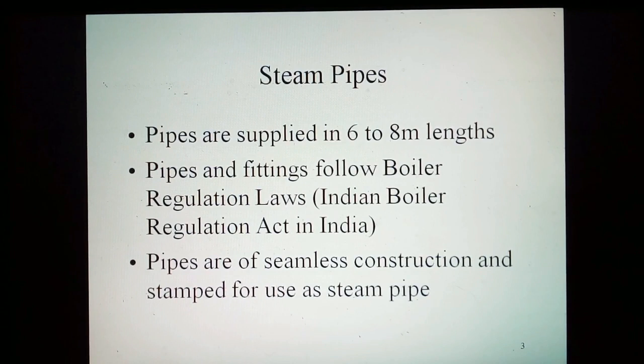Typically, pipes are supplied in 6 to 8 meter lengths. The pipes and fittings used are as per Boiler Regulation Laws, the Indian Boiler Regulation Act in India. The pipes are of seamless construction and stamped for use as steam pipe.